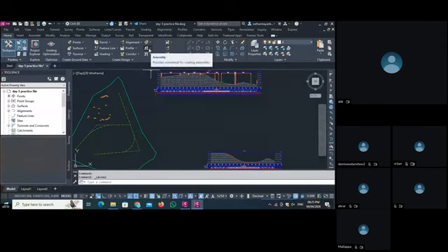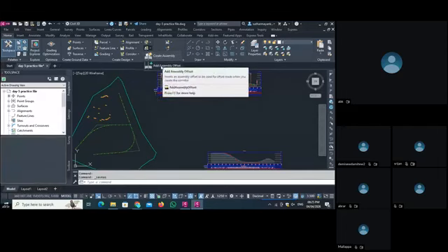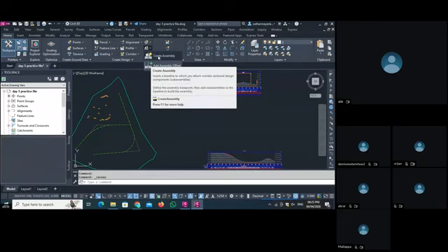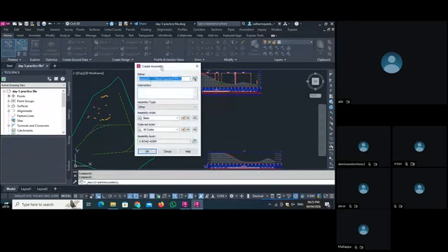if you put your cursor here, it will show an assembly here in the Create Design ribbon bar. In the ribbon bar, when you come here in Create Design, you can see your subassembly part here. If you click here, you see Create Assembly. So we are not using this. We are using this Create Assembly. As you select Create Assembly, again it will give us a dialog box.